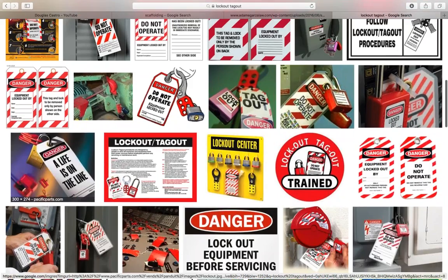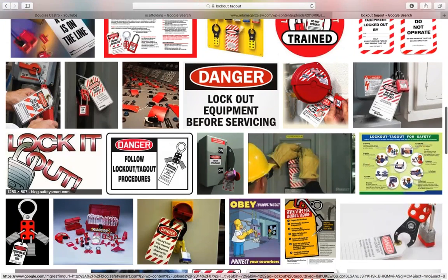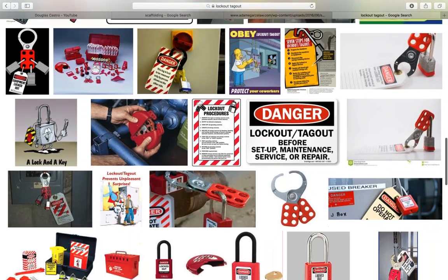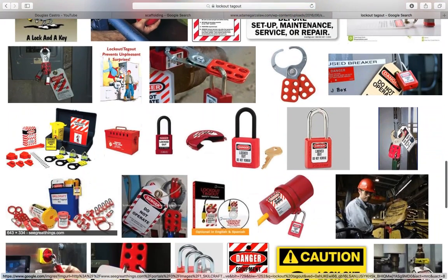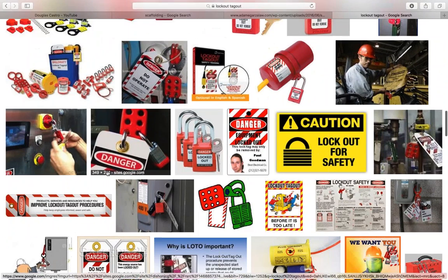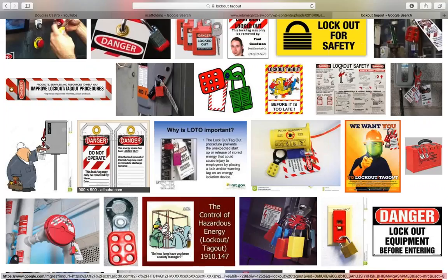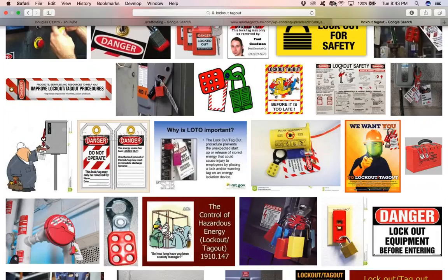Is it as safe? Depends, right? It really depends on, I guess, what the work practices are at the facility. I tell you what I say is I always prefer a lock, but I also understand sometimes it's going to have to be tagged out. And OSHA says that we must show that our tag process is equally as strong as our lock process. The only way I can tell you folks that I can do that and assure that is that I'm going to have to take the same disciplinary process, right? The same disciplinary practice with employees. I'm going to have to discipline an employee who pulls a tag because it's a 50-pound tag weight, tensile weight.